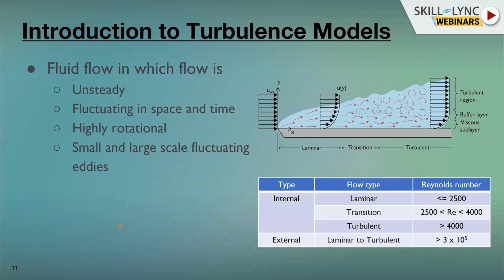We will touch upon an introduction to turbulence models, because whenever one starts solving industrial fluid flow problems, the fluid flow will always be turbulent. Turbulence modeling is altogether a vast topic, and it is taught as one full paper in the course curriculum during MTech. But in this short time, we will see the practical side of what turbulence models need to be used in what situations.